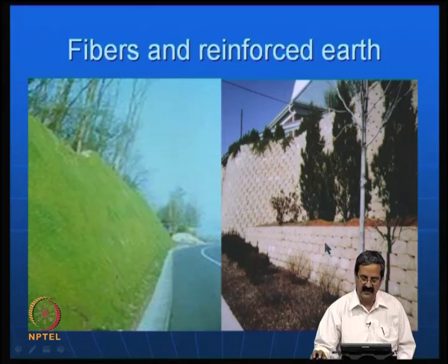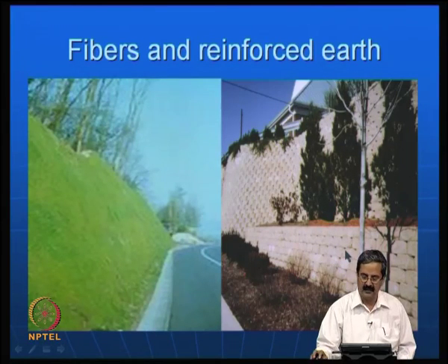So, this is another case of a reinforced earth wall. What you saw previously was a simple reinforced earth wall. This is actually a 2-tier retaining wall, where depending on the profile requirements, whatever profile you want, one can construct nice slopes. The facing elements here are what are called modular blocks, and the native soil will be behind this.